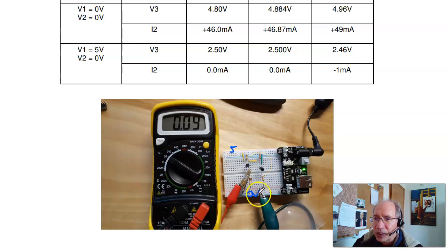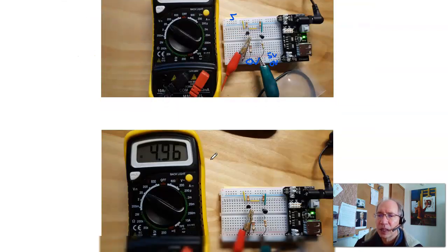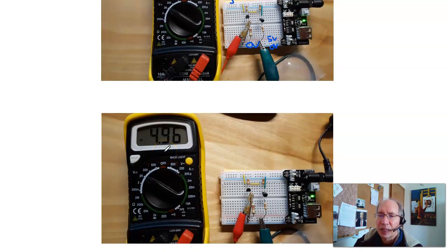Apply voltage at them. You basically move the wires up and down, whether it's 5 volts or 0 volts. And what I get is when it's supposed to be 0 volts, I'm getting 0.09. Again, we're assuming 0.2 ballpark when the NPN's turned on. At 5 volts, or 4.8 volts, I'm actually getting 4.96. Again, closer to ideal than I expect.